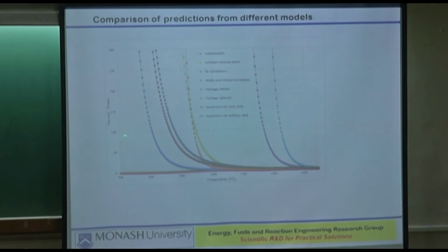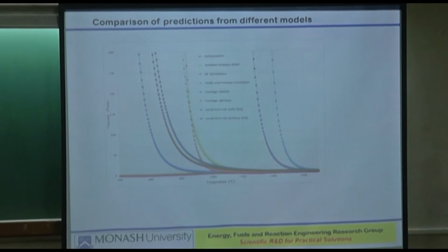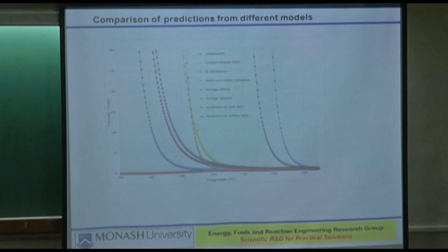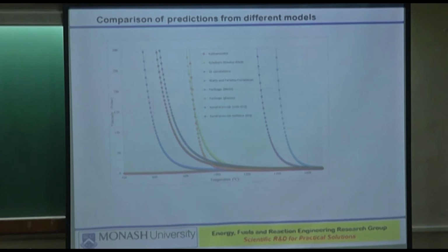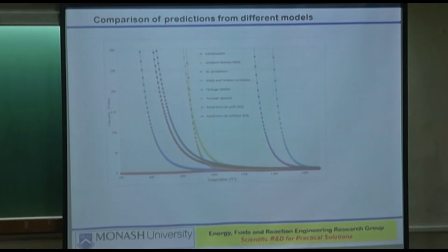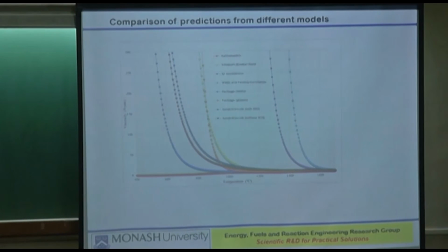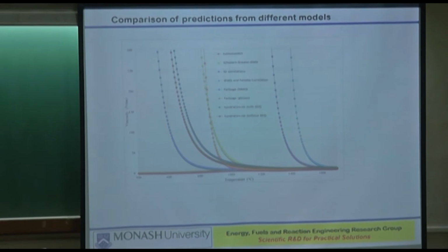And then I look at the lower limit and then the upper limit of temperatures for the 100 to 250 poise, which is dictated by the gasifier manufacturers. I see that the temperature here is actually quite low, and at that temperature it will be semi-solid, it will only be partially melting, and possibly, even though that is what the model is predicting, it will not actually flow down.